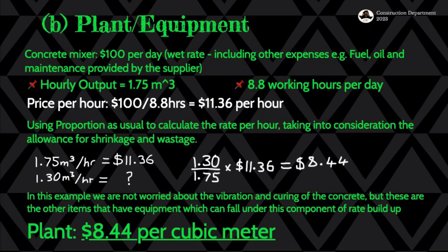And then you're going to see that here we're just going to be dealing with the concrete mixer, assuming that we are going to be using foundations, and we're not going to need a vibrator. There is something that we call a vibrator, which allows for the removal of air spaces within the concrete when it is deposited, to ensure that there is a homogeneous achievement of the bonding of the elements within the concrete. So we have to also factor in that one if it's needed, but in this case we are assuming that it's not needed. That's one thing I also need to highlight.